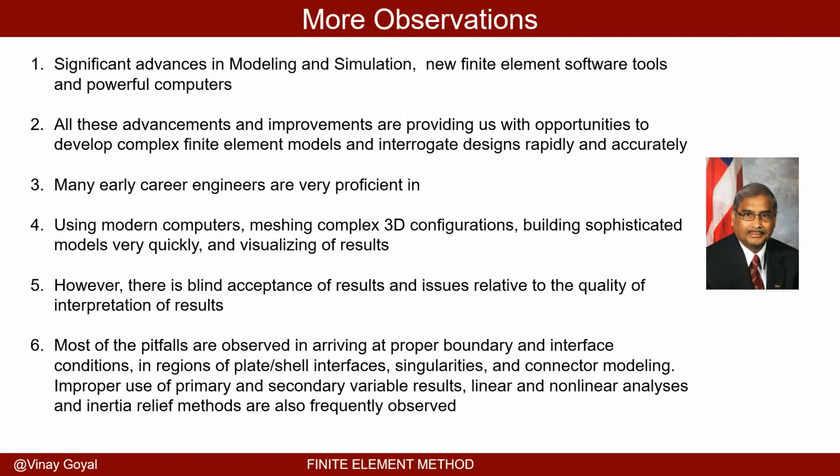A lot of times you have to make sure that the global equilibrium checks are there. And once you put a load, the displacement under the load is the maximum. That's where it should be, unless you are working a cantilever with a middle load someplace. There are only very few exceptions where the displacements are much larger than where the load is applied. So you have to keep track of all of that.